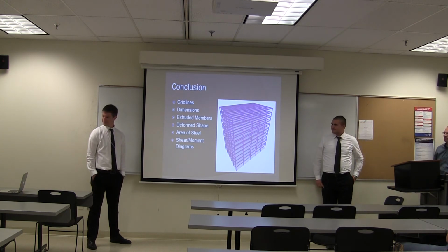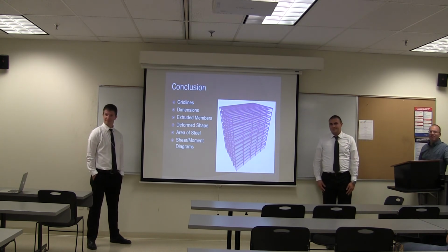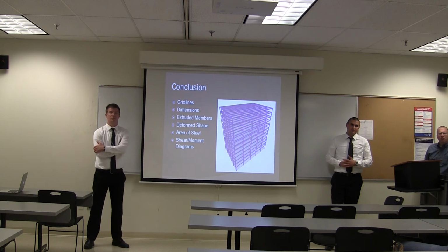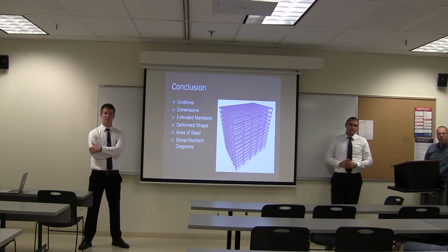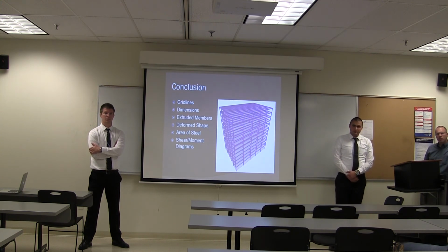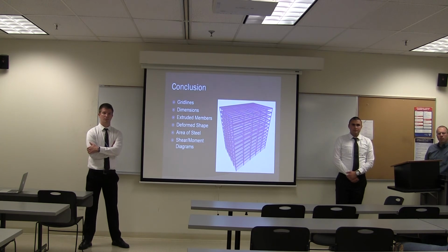There is an issue with that project, you have to have them as a column, right? It might happen that if you design as beams, it doesn't allow you to put shear reinforcement. For me, I had wind loading in my parking garage in the senior design. I had some members failing; for gravity load it was fine, but for shear load it was failing.